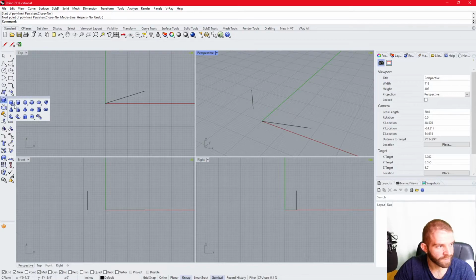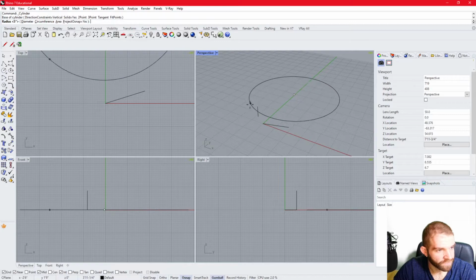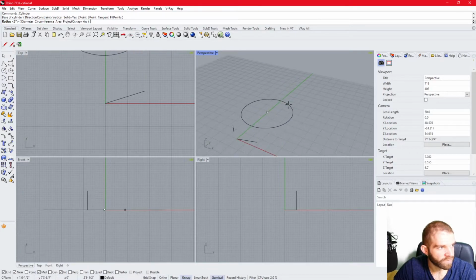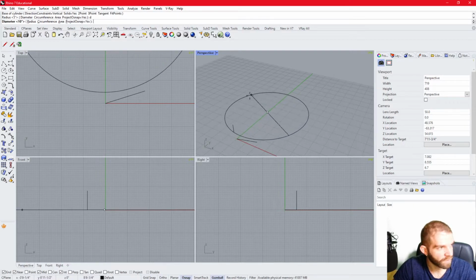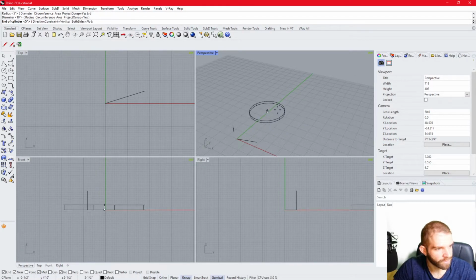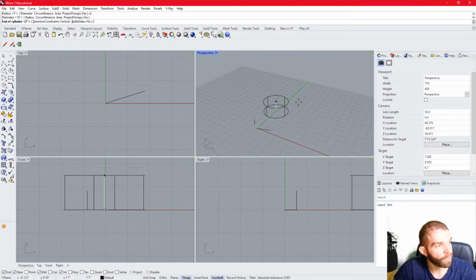So we can select any one of these. I'll go ahead and select a cylinder. Again, we can follow along with the command prompt: base of the cylinder, solid, yes. So we'll take a look at that solid thing that we were talking about. If I click over here to draw the center of a cylinder, now I'm establishing a radius, and I have the option to change to establishing a diameter instead. By typing D, I change to diameter, and I get the line that reads the diameter. Now I'm establishing the height. I can also have an option here that says both sides no.